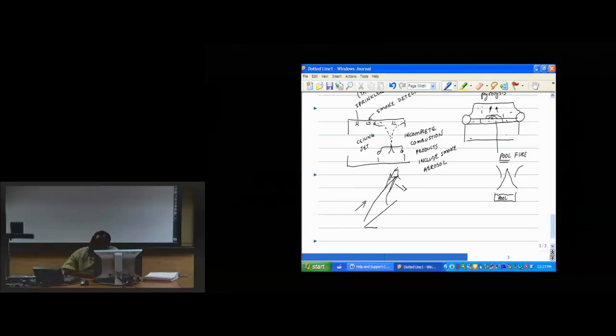So we're getting heat transfer from the flame downwards, as compared to what might occur if you're trying to spread in the opposite direction. Spreading in the opposite direction is challenging because, again, the flame wants to stand up and move in this direction, and so you're not getting quite as much flame area as in the case where the flame is spreading upwards.